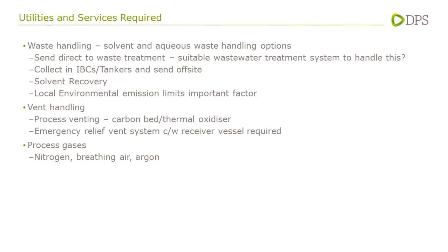Further implications of solvent are the consequences of solvent emissions to the atmosphere. Although this would be dependent on the environmental legislation applicable for the site, it is likely that some sort of emission treatment is required to reduce the concentration of organic solvents emitted to the atmosphere. This could involve treatment ranging from the use of activated carbon beds, thermal oxidation, or cryogenic treatment, which, given the previously mentioned requirement for gaseous nitrogen and the likely requirement by the lyophilizer for liquid nitrogen, could be a good option for a new build.